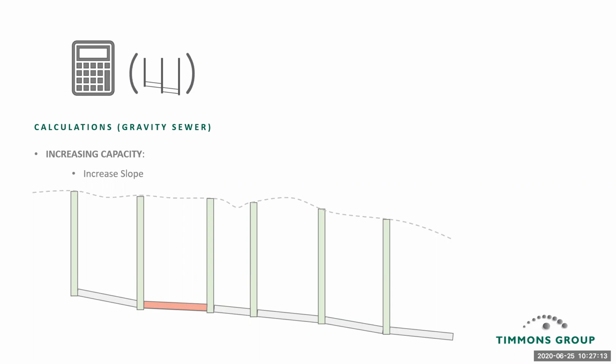The importance of the profile is that if we change the slope of one pipe to correct capacity deficiencies, chances are that change will have to be chased downstream in order to make the elevations work. So this one theoretical pipe that caused capacity problems actually results in the need to replace potentially 4 pipe segments in 3 or more manholes.